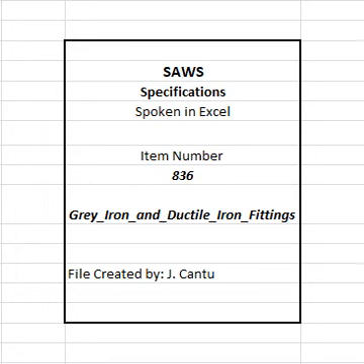836.4 Materials. The materials for gray iron and ductile iron fittings installation shall conform to the latest provisions of American National Standard for Ductile Iron, ANSI/American Water Works Association, AWWA, C153/A21.53, compact fittings 3-inch through 64-inch and ANSI/AWWA C110/A21.10, full body fittings 3-inch through 48-inch for water service or most applicable approved equal provisions, and the specifications contained within the latest revision of SAWS material specification. Item No. 10-10, Gray iron and ductile iron fittings.